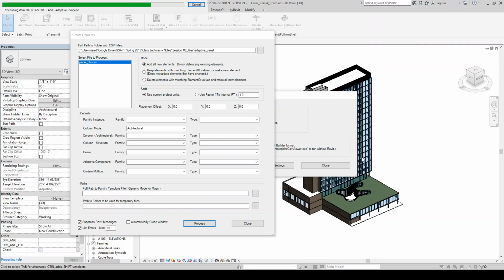So we can actually see in real time these panels that are coming in. We'll notice that they're actually pointed the wrong way. So what we'll do is we'll flip them in Revit. But basically it just means that if we wanted to correct that for a future workflow, we would basically just change the order of the points that we're placing to reverse it.